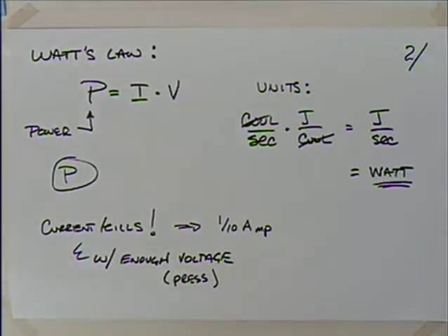Now, the question that oftentimes comes up at this point is how much voltage is enough? Well, it really depends. Is your skin wet? Is it dry? Is it in good repair? Does it have a cut? It can vary. I've actually had a cut on my hand and been able to feel 12 volts. Some people will test a battery on their tongue. I'm not sure how smart or fun that is, but different parts of the body, whether wet or dry, all changes things. I do know that things get quite a bit more dangerous at 36 volts, 48 volts, or on up from there. That's quite a bit more dangerous than 12 volts. So something to think about.